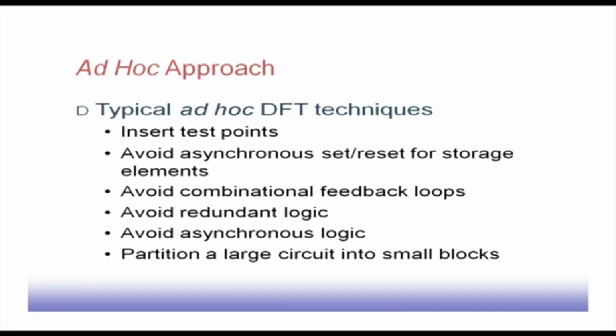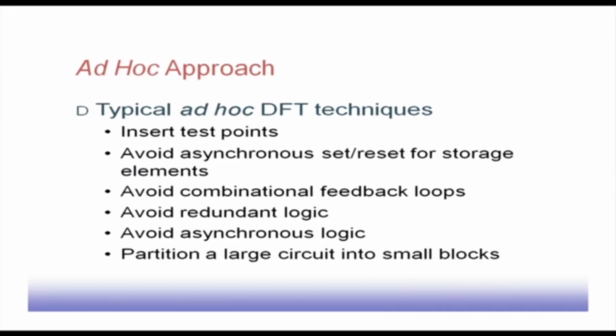Then asynchronous logic. If we can ignore asynchronous logic, then we know that the entire operation is synchronous with some clock signal, so my testing can be concentrated on the individual clock transitions only. Scan shifting and all that can be done easily, but an asynchronous system does not have a clock, so it becomes difficult to control the overall test session. And if I am allowed to partition a large circuit into small blocks, that can be helpful, because it will help us concentrate on smaller parts of the circuit, and the testing process may be simpler.